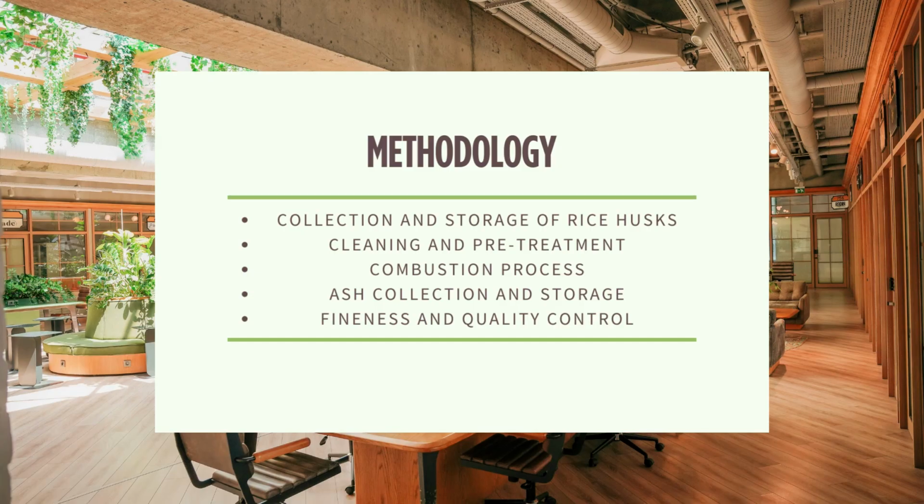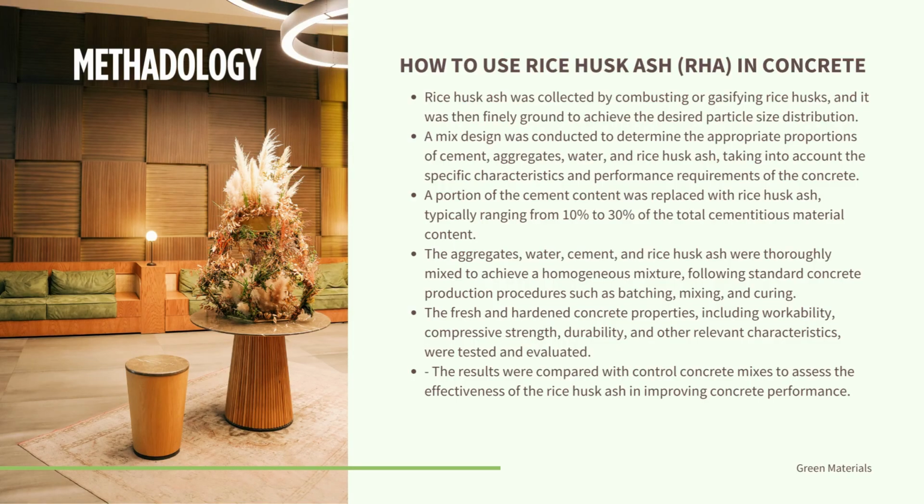So the methodology, which is how the rice husk ash is manufactured, starts with the collection and storage of rice husk from the paddy field, cleaning and pre-treatment, and the combustion process, which is the burning of rice husk. The ash is collected and stored, and the rice husk ash is ground fine, with quality control, to produce finer particles.